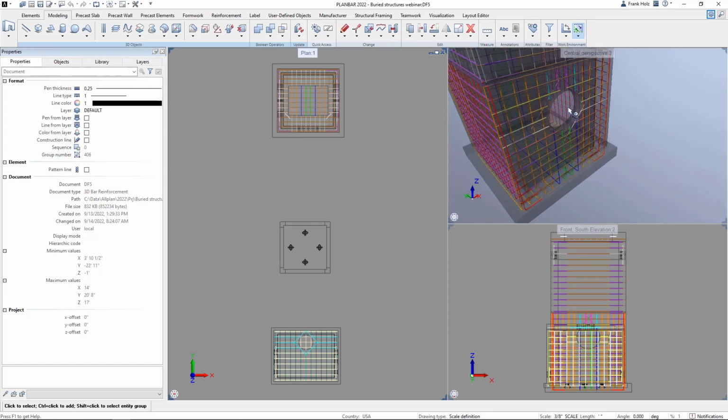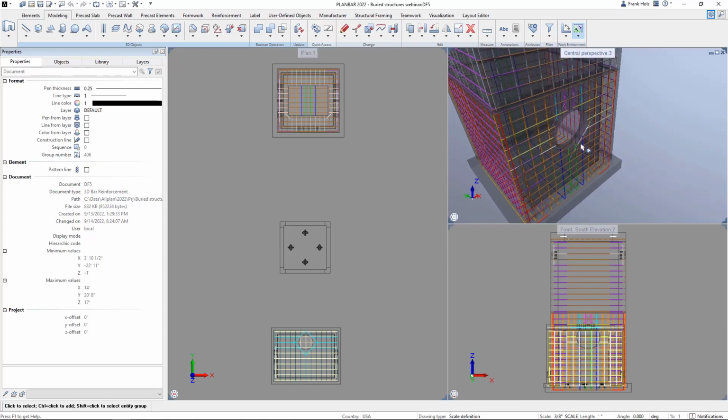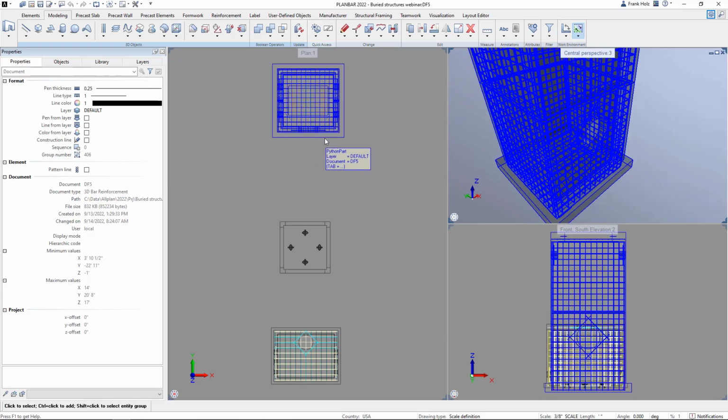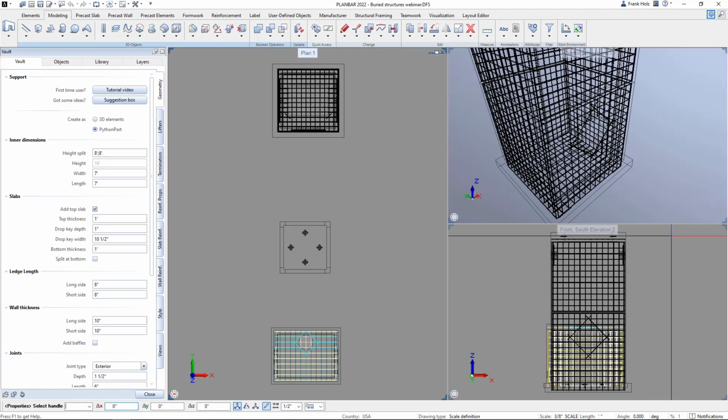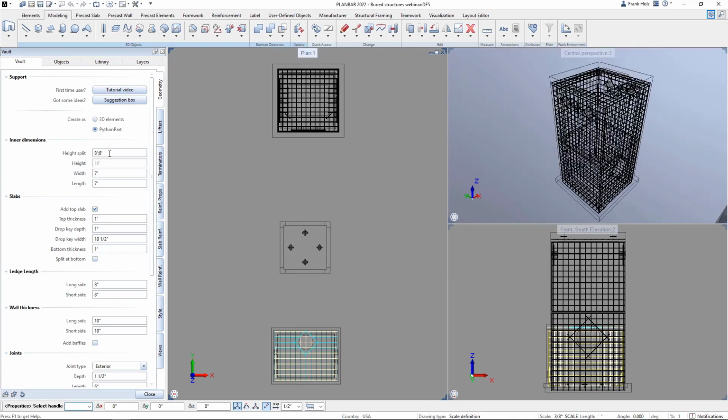So we can see that it's going to automatically hold back our bars around openings. It's going to create supplemental replacement steel. Replacement steel, every time you cut a bar, you need to replace it on the sides. If I double click on any objects, you can see that they're parametric. They stay parametric, kind of like our culvert. You enter a series of parameters.